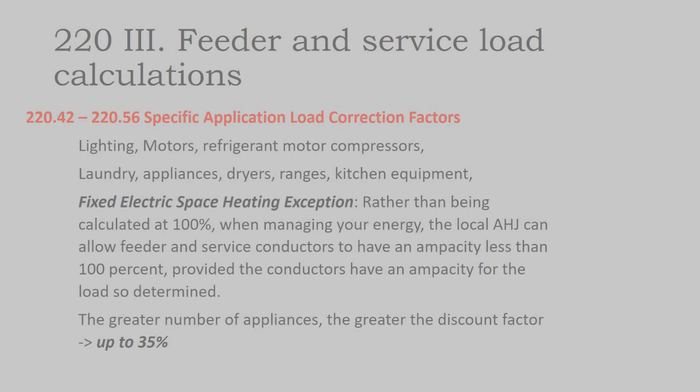And so what this is saying is, there may be areas where, if you're employing on-site energy storage, like a battery bank, your electric service may be allowed to be undersized. We've seen that happen with electric space heaters. We also see some undersizing allowances based on the larger usage that you're having.